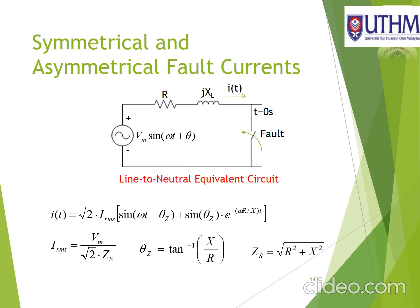From this equation, we can get the IRMS, which is equal to Vm divided by square root 2 divided by Zs. We also can get theta, which is equal to the inverse tangent of X divided by R, and also we can get Zs, which is equal to this formula.